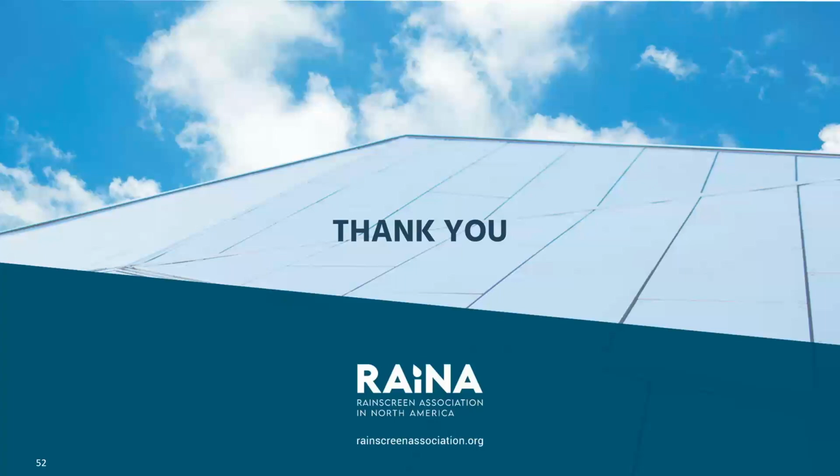Thank you. And then what are some recommendations for ventilation and drainage for something like stucco? So yeah, stucco is a great cladding material, but we all know stucco does crack over time. In terms of water management, it cracks and it can absorb water, so it's a great idea to drain behind the stucco and ventilate it. That's where we see a lot of those drainage mats behind stucco with a lap over it, so you can let water and air drain out of the wall behind the stucco.